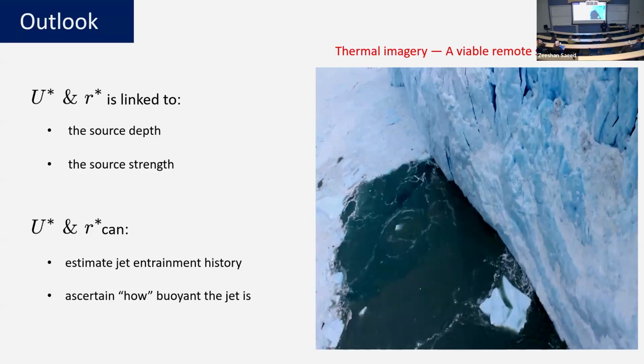Even in a situation like that, can we assume that there's no surface perturbation? Well, that would really depend on what the perturbation is relative to the largest length scale. If the wave is like 10 feet big, that's going to be problematic. But over here, if it's 3 or 5 centimeters of surface perturbation, the characteristic length scale is likely to be much larger than that. So it really is a balance between two distinct length scales.